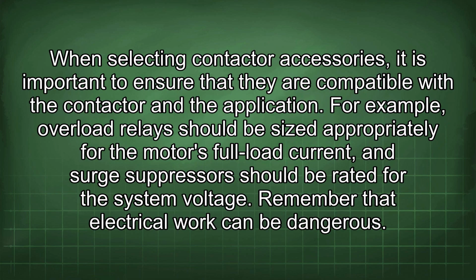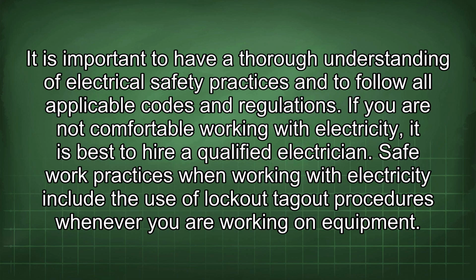When selecting contactor accessories, it is important to ensure that they are compatible with the contactor and the application. For example, overload relays should be sized appropriately for the motor's full load current, and surge suppressors should be rated for the system voltage. Remember that electrical work can be dangerous. It is important to have a thorough understanding of electrical safety practices and to follow all applicable codes and regulations. If you are not comfortable working with electricity, it is best to hire a qualified electrician.